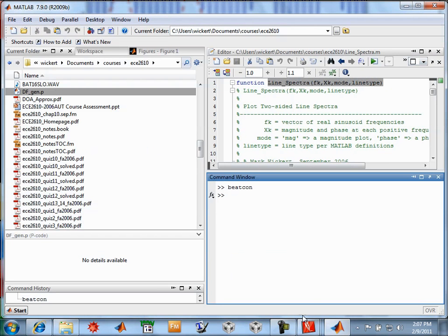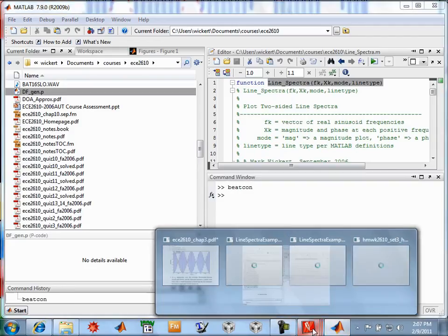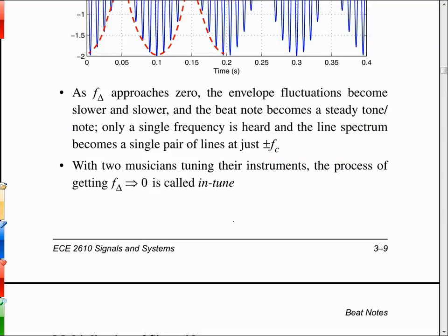You're going to have another lab on synthesizing bell tones, and that one's quite a bit of fun too, where you're looking at how to create a certain type of timbre by changing some parameters in a waveform called frequency modulation with an envelope decay to synthesize a bell tone sound. In the end, it's not going to sound like a real bell, but it's going to be a simple approximation to some type of bell tone sound.